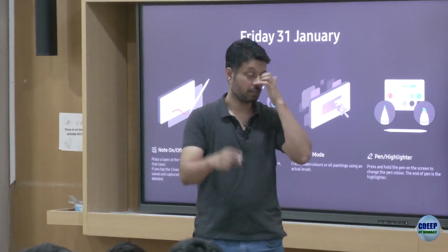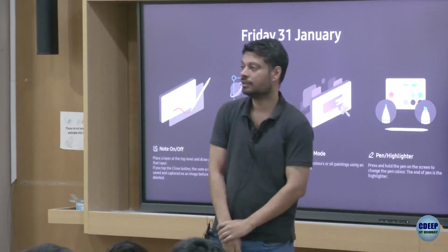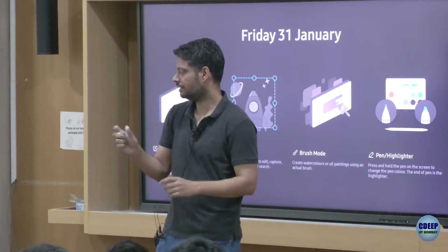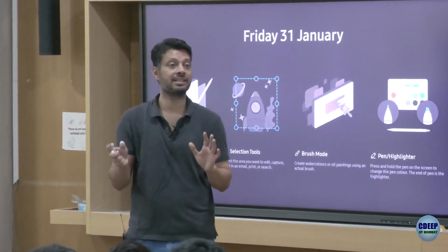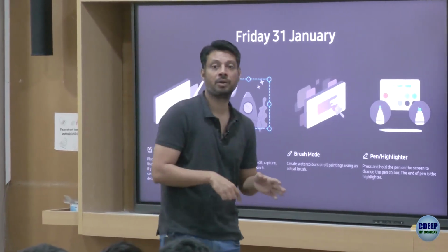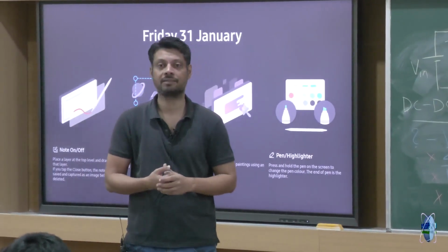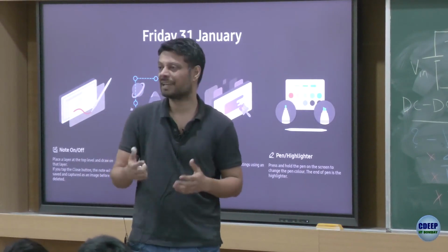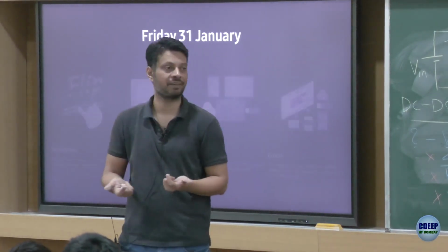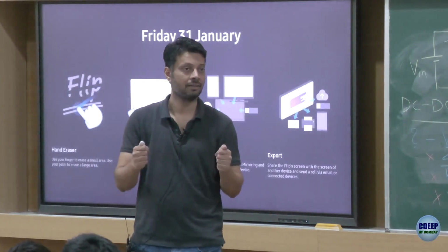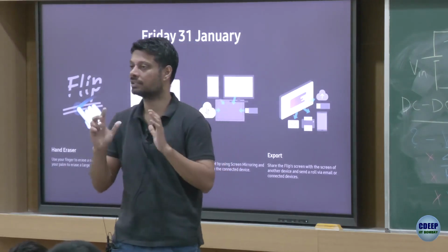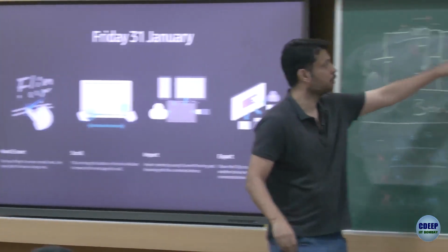Just go by first principle, write it as an integral. That would give you a little bit of insight, right? Of course, you can still consider the same assumptions as we did before. What was the assumption we considered last time? Output voltage ripple is really small. Last time actually we didn't use it to calculate the average voltage, but now you would really need it. So you can consider the output voltage ripple to be very small.